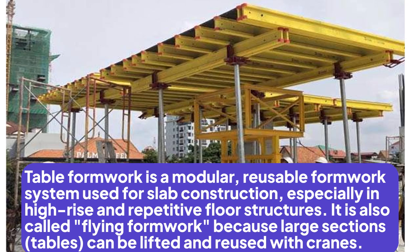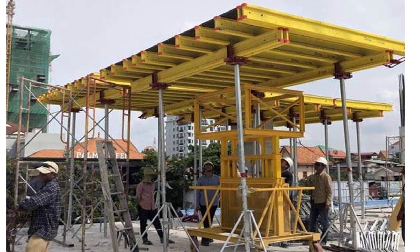It is also called flying formwork because large sections of these tables can be lifted and reused with the cranes. That means it's forming the table, and after deshuttering, the same table can be lifted and placed in the new area. So that is why it's called the flying formwork. Sometimes it is also just called the table formwork.